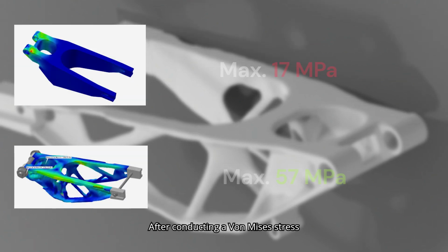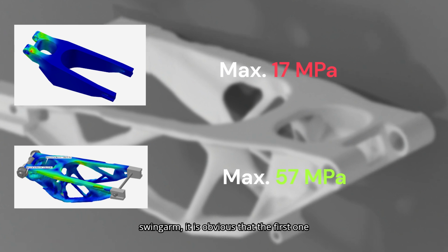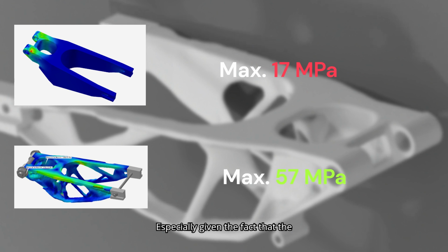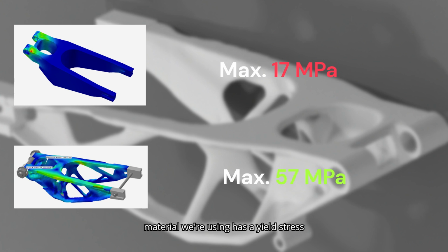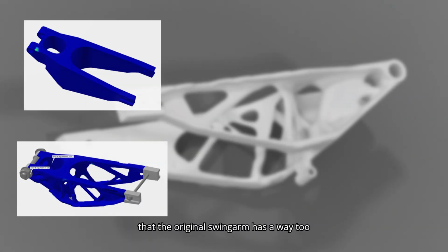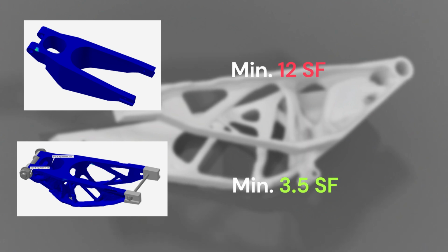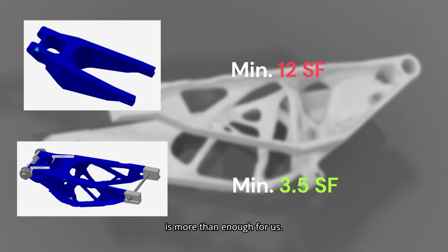After conducting a von Mises stress analysis on the original and optimized swingarm, it is obvious that the first one is way too strong, especially given the fact that the material we are using has a yield stress of 200 megapascals. In the same way as before, we can see that the original swingarm has a way too big safety factor, and the 3.5 the optimized one has is more than enough for us.